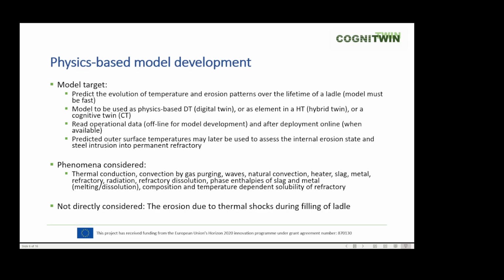So we could call it semi-online. And in our case, we see that the predicted temperatures for the outer surface of the ladle could be used to assess internal erosion states and possibly steel intrusion into the permanent refractory. This point we will come back to briefly later.